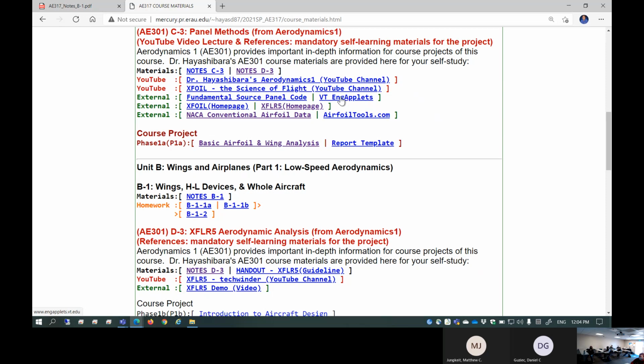You are going to create your own shape using a bunch of vortex panels, and how many panels depends on how many data points you provide. If you provide very high resolution data points, like creating this shape using 20 data points, 200 data points, 2,000 data points, it's going to create a much smoother surface.